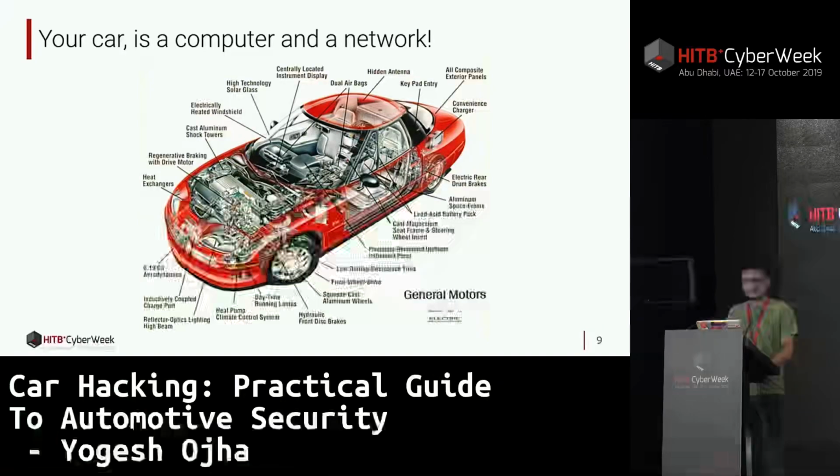So just for an example, take an airbag. You have these tiny little computers that make very, very fast decisions. Modern airbags are looking continuously at the seat position, the weight of the passenger or the driver, whether the seat belt is on or not, what the crash condition is, what the aftermath is, and many factors that run in an infinite loop to decide whether the airbag should be fired or not.